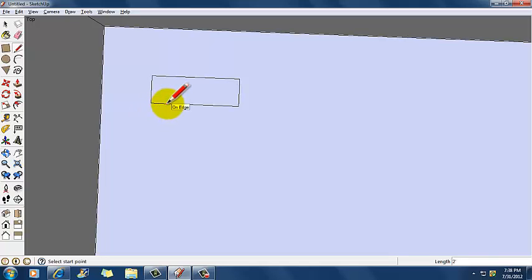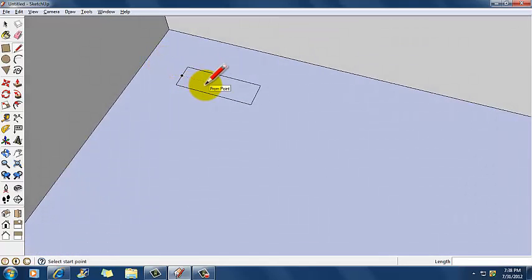So just to keep this thing its own, let me orbit a little bit here. Just to keep my shape its own thing, I'm going to pretend that I've got a base that I'm going to make on this display case. And so I'm going to bring a copy of that shape up. So I selected my push-pull tool. I'm going to click on Control. You may not have to click on Control. If you didn't click Control twice before, then you're good to go. If it's got a little plus beside it, you're fine. So I click on Control to get the plus.